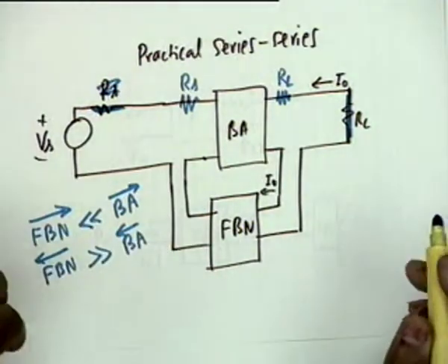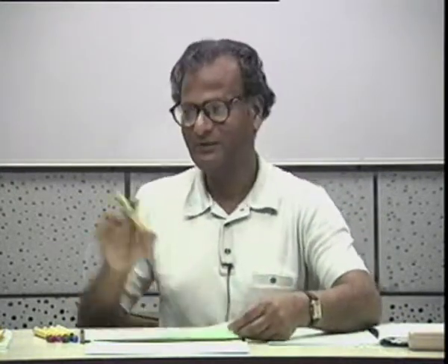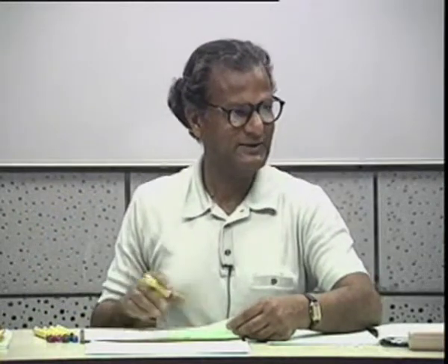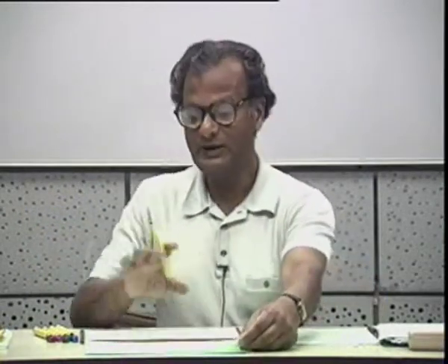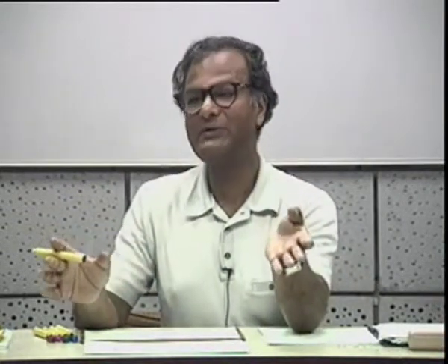This is because the appropriate parameters here are the Z parameters, small z, the impedance parameters. Let me justify now the procedure. But before justification, can I complete this and come back here? Okay. Can I complete the beta circuit without caring what the appropriate parameters of the feedback network are?